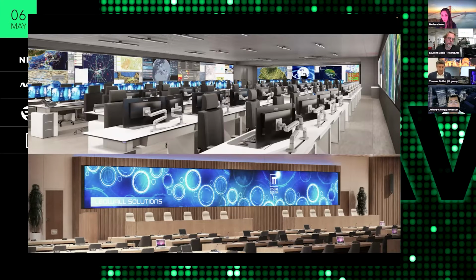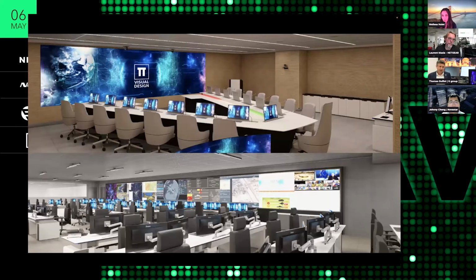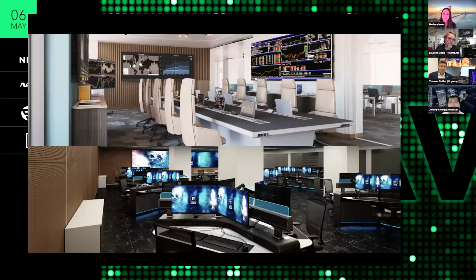And those LED video walls are nothing like 4K LCD displays. First, they are not 4K, and they are not even 16:9. They don't have a standard resolution, and they don't have any HDMI input. So you need to control them with a system based on a sending card and a receiving card in every cabinet of the LED wall. So this is a challenge, and this adds to all the other challenges that the system integrator will have